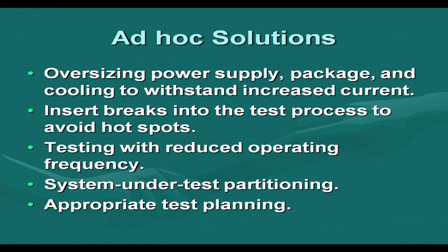If a total of 1000 patterns are to be applied, maybe we apply 100 patterns, take a break, then again we apply 100 patterns, take some break. So, that will allow the system to cool down. When it cools down, then the static power consumption, the leakage power consumption, will come down. So, as a result, test power can be reduced.